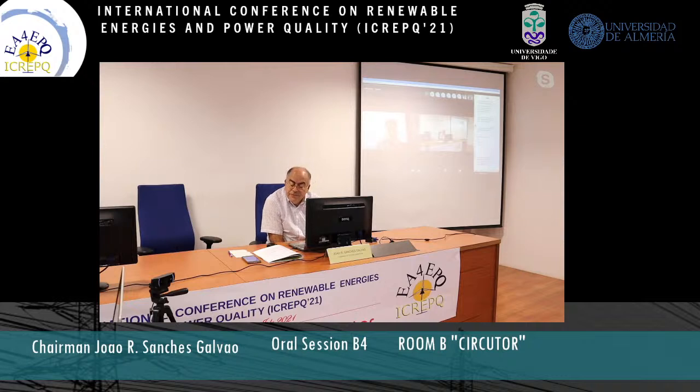And to reduce the cost of this power electronic interface, if we are using semiconductors that are rated for a lesser power and we are associating them in parallel or in series, we can achieve the same power while reducing the cost. I think this is one of the axes that a manufacturer can use to improve and to reduce the cost of the power electronics used to connect the wind turbines to the grid.